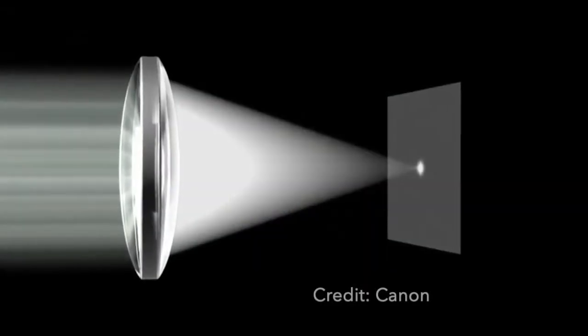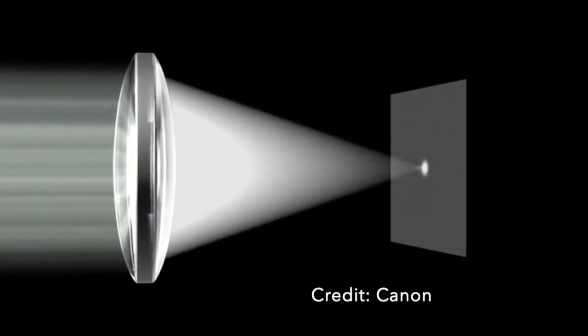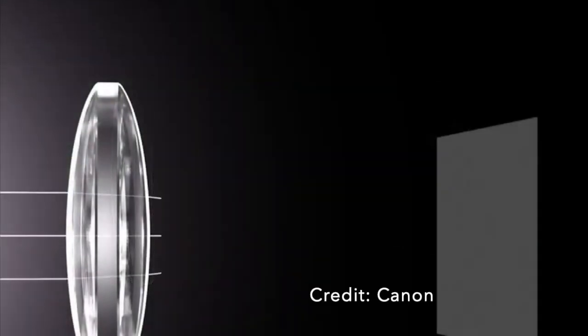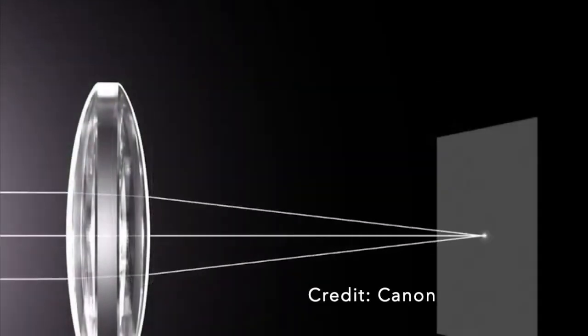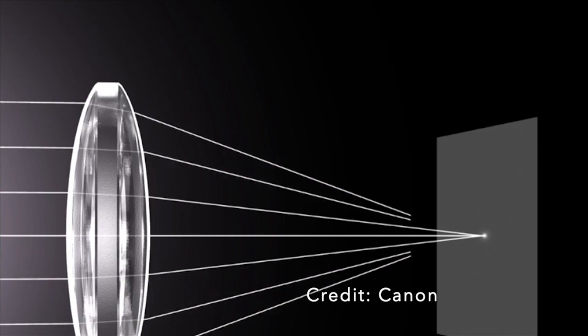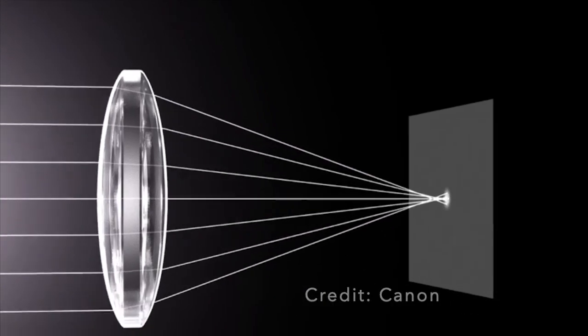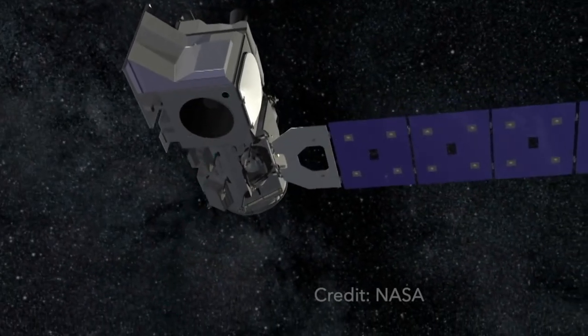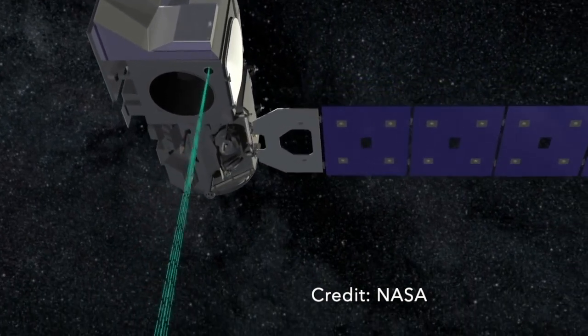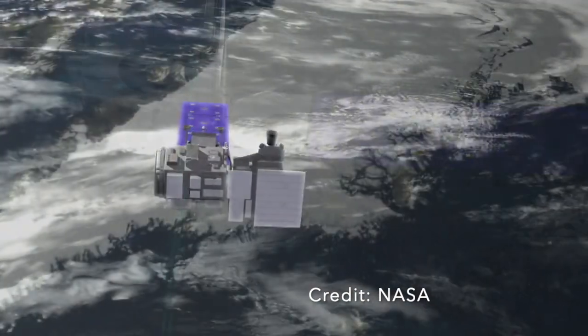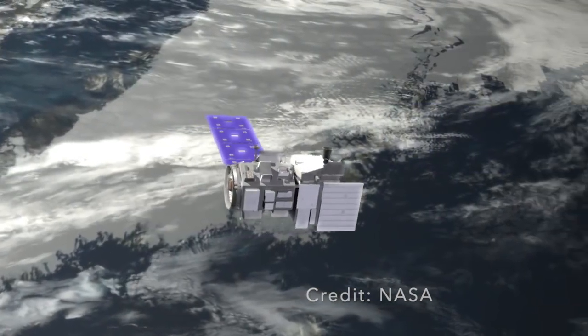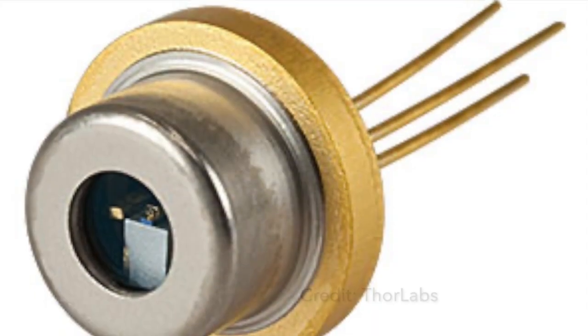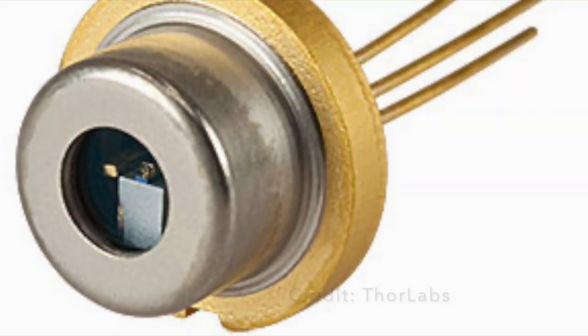Considering the large distance from the satellite to the ground station, the laser will need to focus to ensure adequate signal strength. This is accomplished by using a lens to focus the beam to a narrow divergence angle. Many commercial lasers were considered to function as a laser beacon, mainly in the near-infrared wavelength range. A 1064 nanometer wavelength diode laser was chosen for the final design.